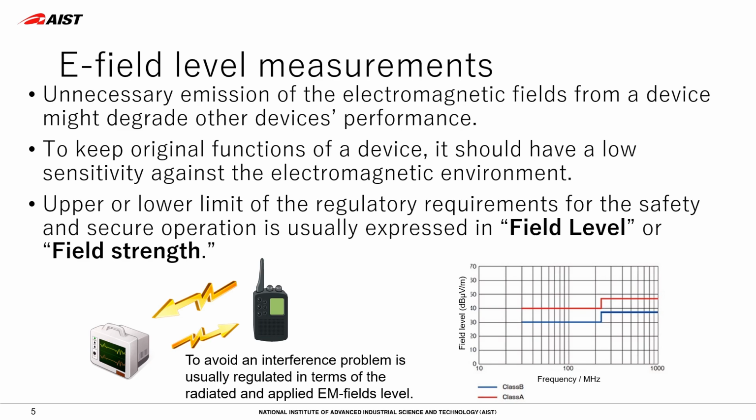Accordingly, careful investigation should be carried out from the viewpoint of electromagnetic compatibility before putting products into the market. Some of you may have been aware already that most of the regulations and standards, not limited to those for EMC tests, require E-field strength measurements. Electric and magnetic field strengths radiated from or impinging on the device are fundamental quantities to be measured, since they are considered to have tight relationships with interferences, such as stability and performance of a device.